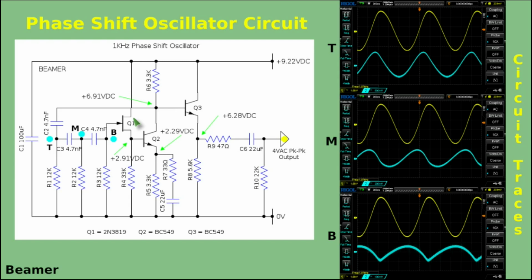But I've added two extra components. I've modified that. One is to include the JFET so that it offers a very high impedance, and the second thing I added was a buffer here. The feedback here is probably the weakest point of this circuit, in that it doesn't offer a very low impedance drive. To achieve that, you would really need to use an op-amp, but because we're looking at discrete components here, I had to strike a compromise.